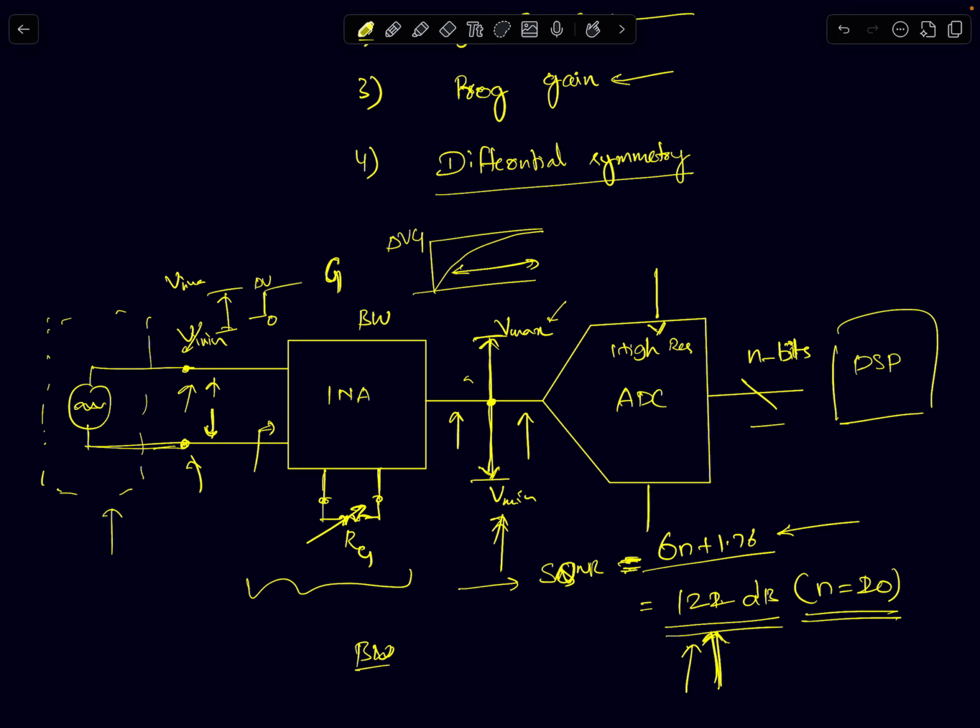Depending on the ADC sampling frequency, how frequently the ADC is going to sample its input, your instrumentation amplifier's bandwidth should be chosen appropriately. Okay, so these are the other things to keep in mind when you are picking an instrumentation amplifier. I didn't speak about offsets, bandwidths and all that, because these are things you will have to worry about for any op-amp based amplifier, whether it's non-inverting or inverting. You will have to worry about those things even there as well.